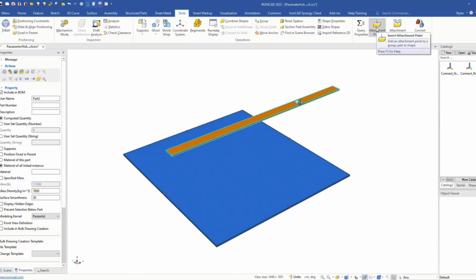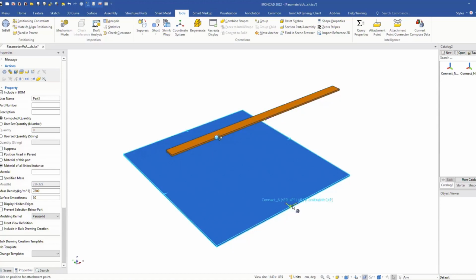Now we'll go ahead and create an attachment point on our part, and I'm just going to create it on the center again on this bottom edge of this part. It's got our Z in one direction. Now this is where you need to keep an eye on your attachment point location. When we drop, we align the Z's, anti-align the Z's, and align the X's. So the X's are in the right location, but if we use this Z on the bottom edge, it's going to flip this thing to the opposite side, so it's going to be upside down. So I can just go into this part, grab that attachment point, and simply rotate it 180 degrees. Okay, now I've got it set, and I just need to give it a name again.